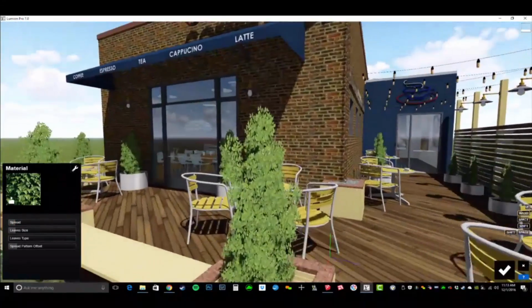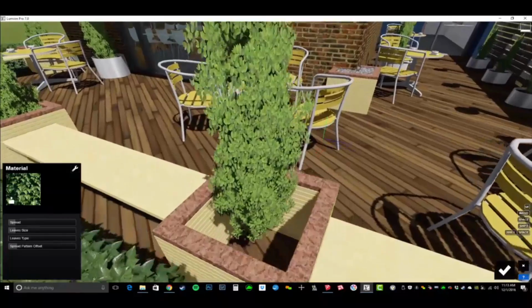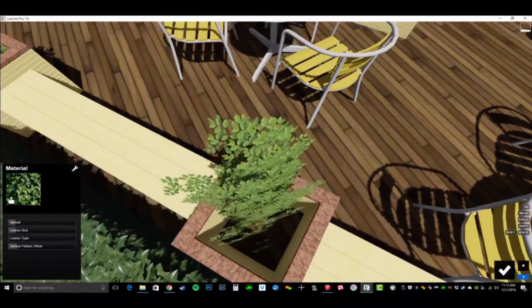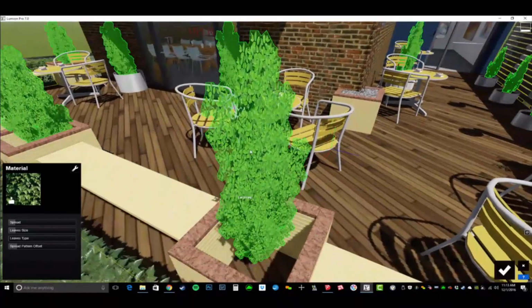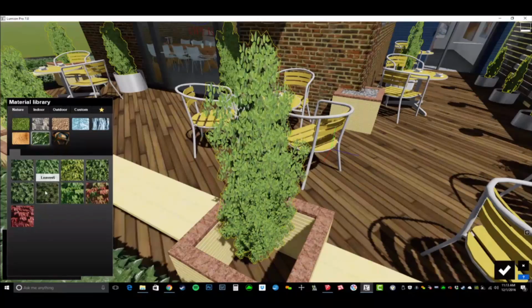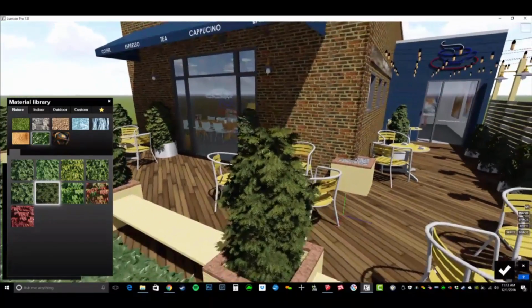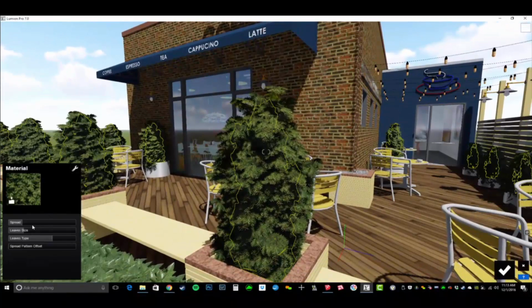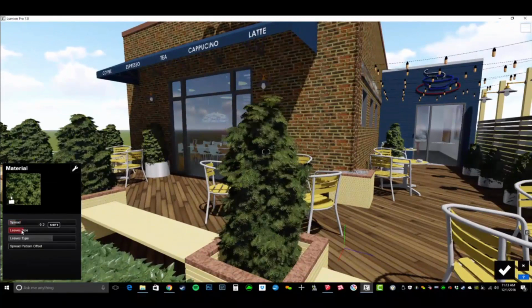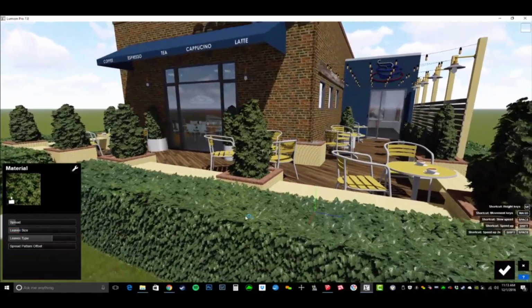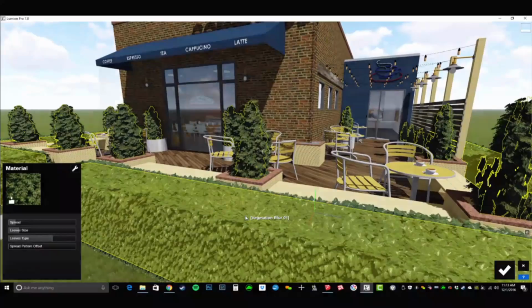Now, check this out. We've got our 2.5D tree. So see how that thing comes in as these faces? Well, the nice thing about this is that now we can click on this and go to our nature, leaves, and let's use more of a pine needles. We'll double click on that one and then drag the spread down, and maybe the size goes down a little bit. So really what this does is it gives you the ability to build your own trees in SketchUp.